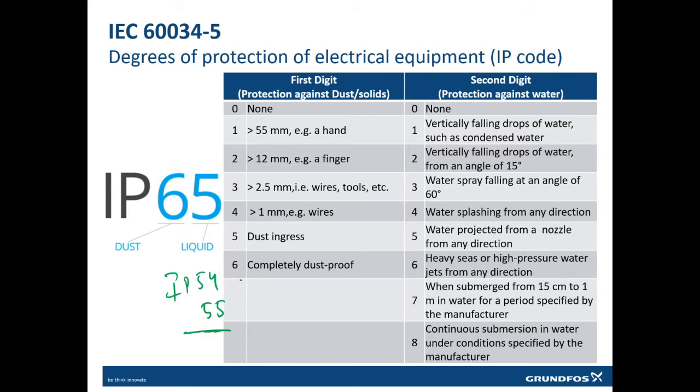So you need to make sure that you are not taking a water pipe and cleaning the motor with the water. It probably will go inside if the water is at very high pressure and the IP is 54 or 55.